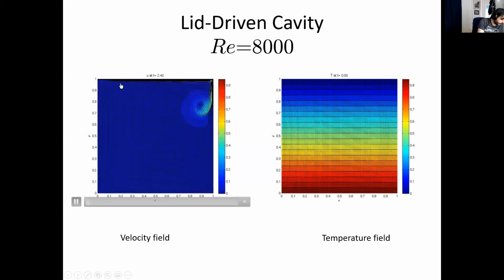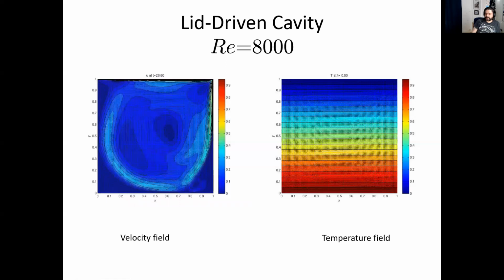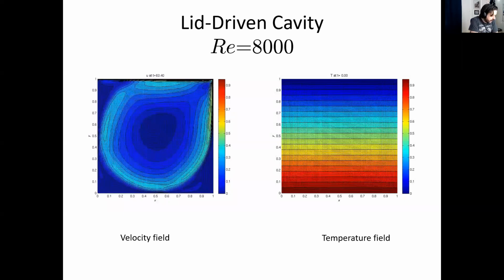Now, if I just plot that again, just to mention again, there's a lot of unsteadiness. It takes a long time until the flow actually settles down. Also here, maybe I can make a comment. People have studied this flow case of the lid-driven cavity using methods of stability analysis, and they have concluded that the Reynolds number above which the flow would never become steady, so it will always be unstable, is on the order of 8,000.